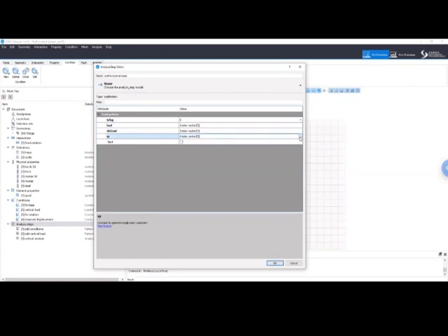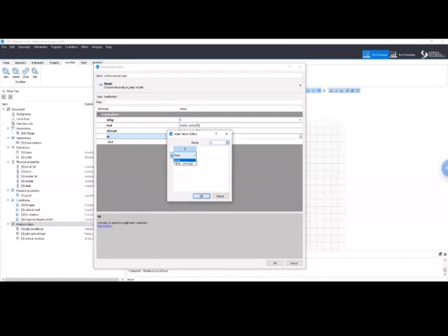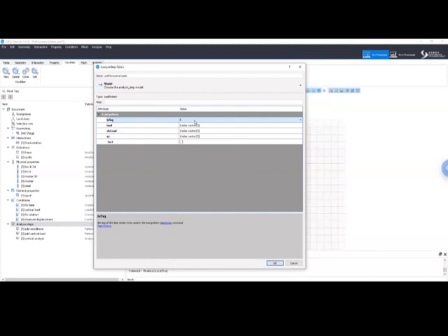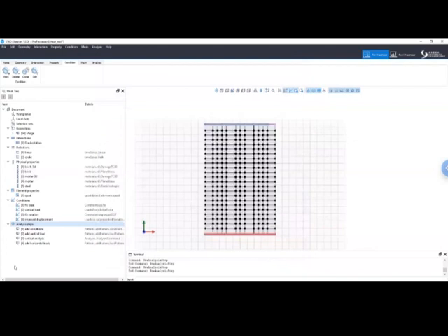So we go under this vector here. We make room for 1 because we have just one constraint of this kind. And we choose the imposed displacement condition that we defined before, as you can see here. We press OK. And now we need to choose the time series. The time series will be the cyclic one. Okay? Let's press OK. So we have the vertical load. And now we can do the horizontal analysis.